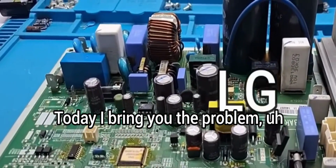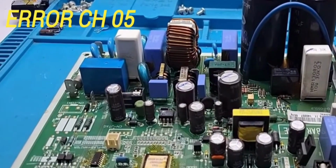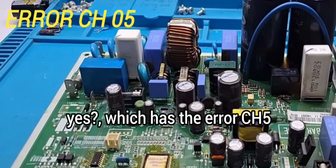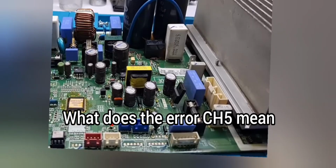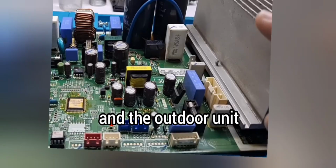Today I bring you the problem of an LG inverter board, which has the error CH05. What does the error CH05 mean? It is the intercommunication error between the indoor unit and the outdoor unit.